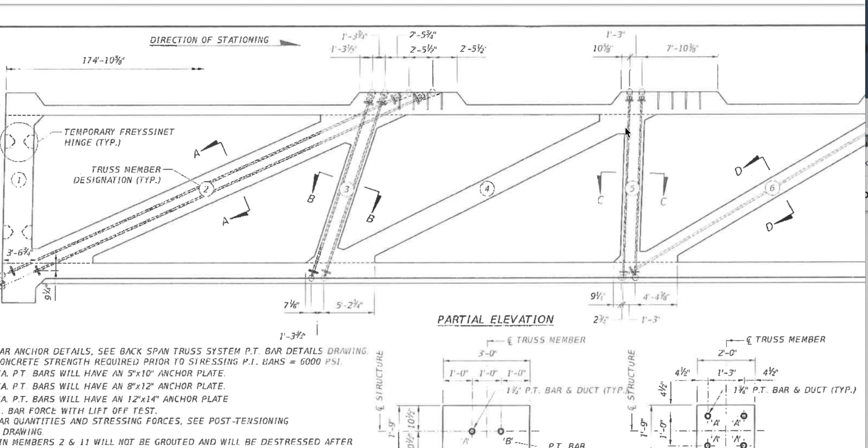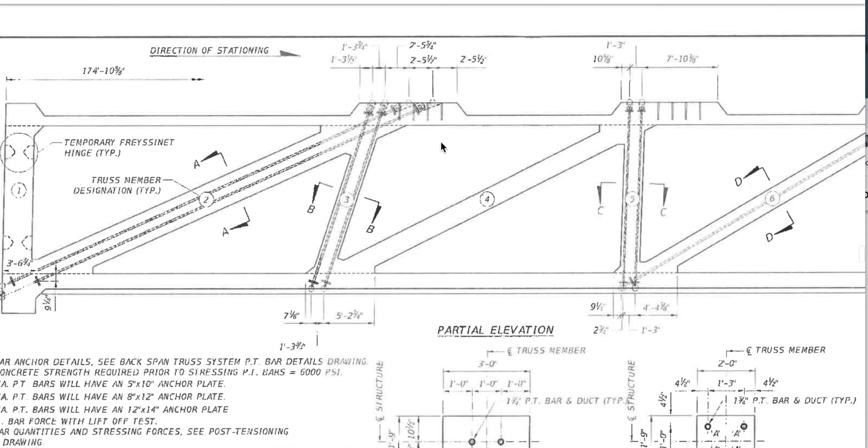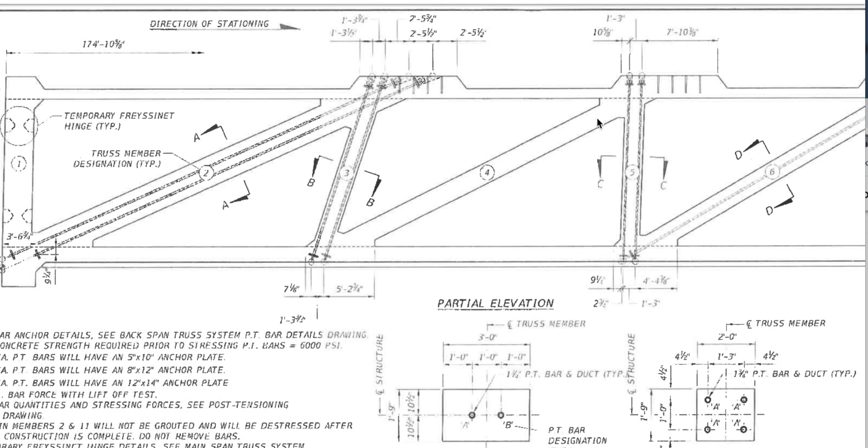And now the tube, the plastic ductwork, will be engrossed into it. That's why if you had concrete, you grouted these closed, now it's going to act as one. But it's still going to be shear. If it's all concrete grouted, the shear reaction is still going to be there, up top here and down here. Remember, it's got some reinforcement, but that's not its intent. It's a stirrup connecting.